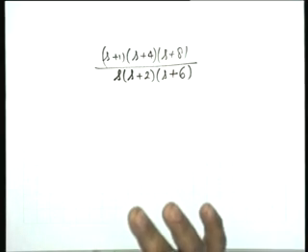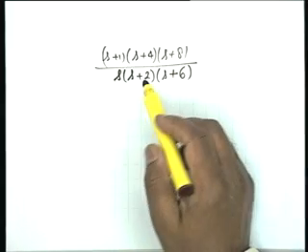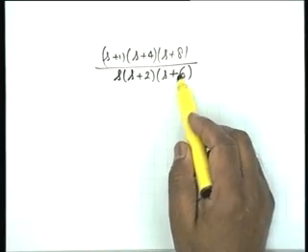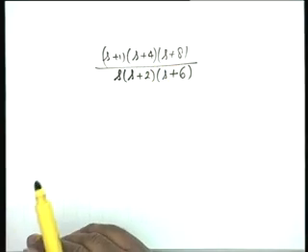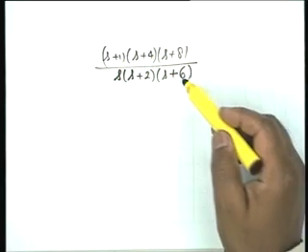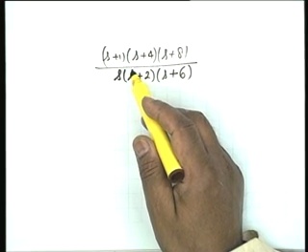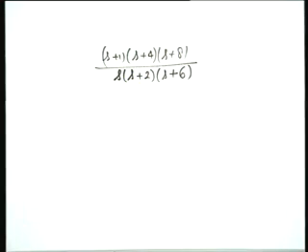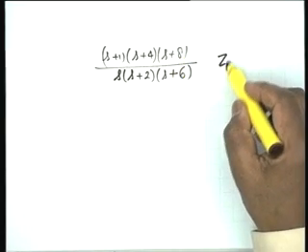First thing is you find out whether it is RC. If it is RC, poles and zeros must be on the negative real axis. Poles and zeros at 0, minus 2, minus 6, minus 1, minus 4, minus 8. So, poles and zeros satisfy that condition. Do they interlace? 0, minus 1, minus 2, minus 4, minus 6, minus 8. Yes, they do interlace. Then, is it an impedance? It has to be an impedance because the first critical frequency is a pole. If the first is a pole, the last must be a 0. Last is minus 8, it is a 0. So, this is indeed a ZRC.